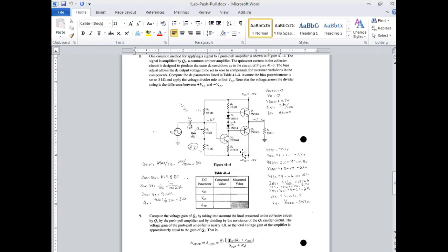Because it generates a Class A output, but it's 75% efficient. Class C's, we use those in RF a lot, but we don't use them in power circuits. Well, we use them in switches. We use a lot of Class C's as switches. We'll oversaturate them, right?